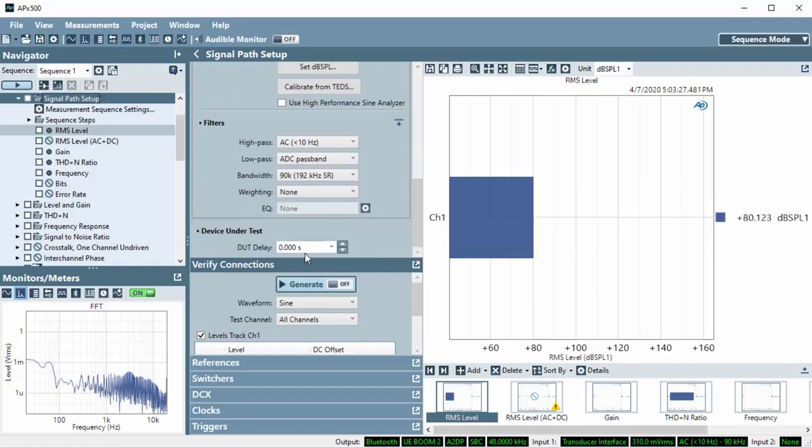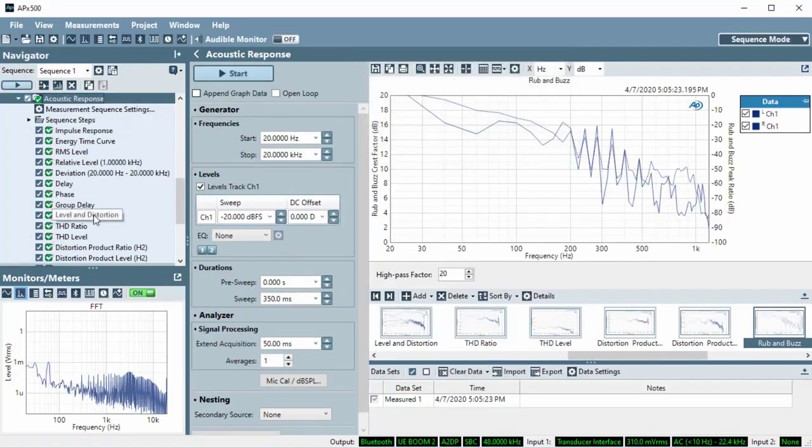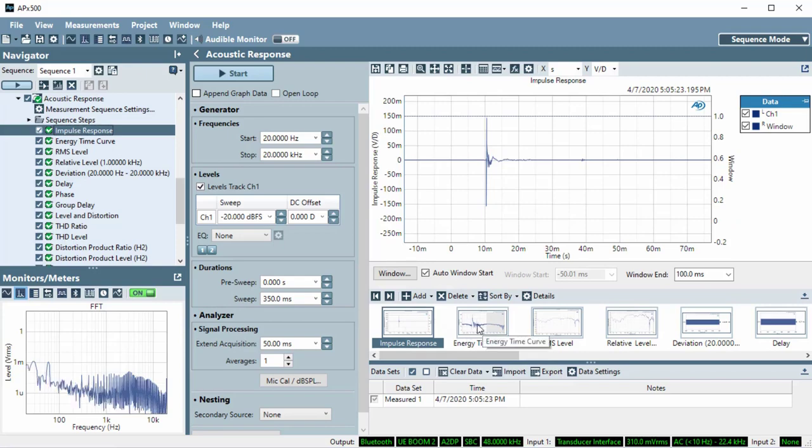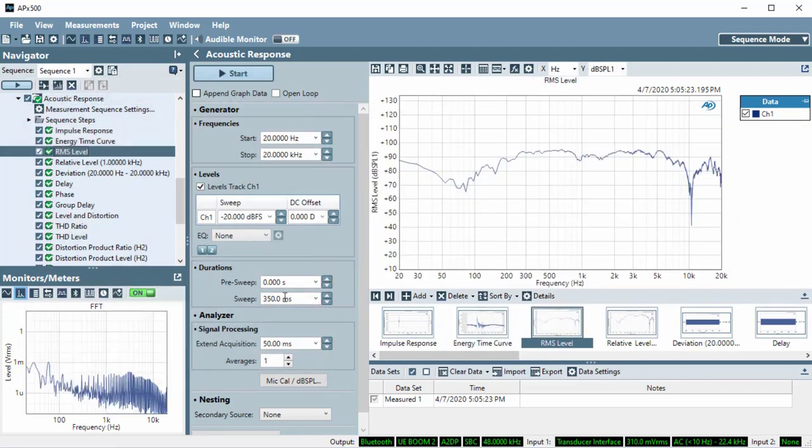Note that the delay can move around a bit, so it might take an adjustment or two to find a reliable value. However, as soon as we make this change, the next run of the test produces a quite good data set. The frequency response is quite flat over the range of about 200 Hz to 9 kHz. With that, we've come to the end of our testing.